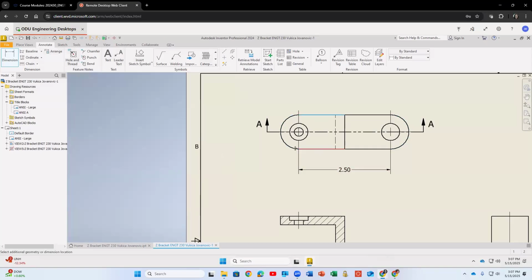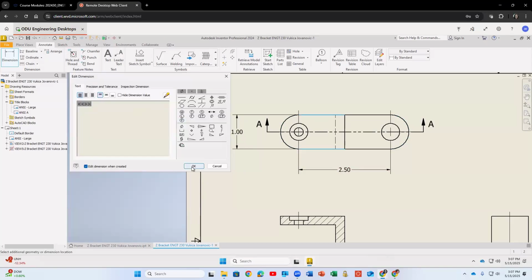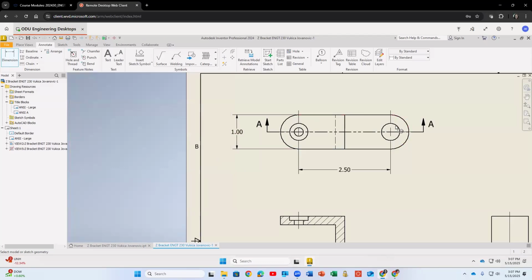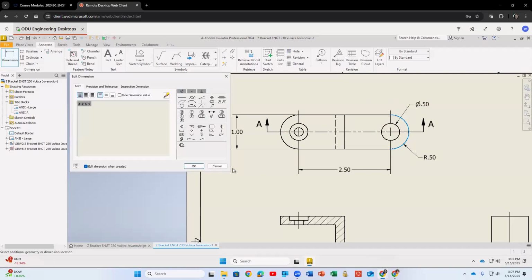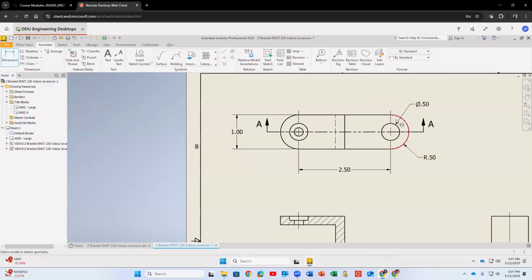I want to have this other one. It's always best if you can dimension circles where you actually see them as circles. Here I have a circle, and then use maybe around 30 degrees, 45, 30. When you dimension circles, don't do it like this, it's too close. Try to be somewhere in the middle, or if you have multiple ones, be at 30, 60 degrees. You see they look more neat. I dimension what's outside, the radius, and I dimension the circle.